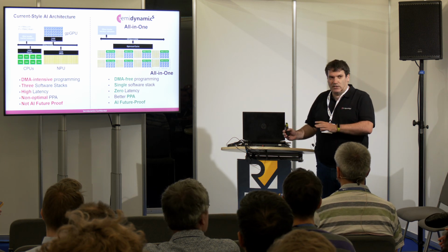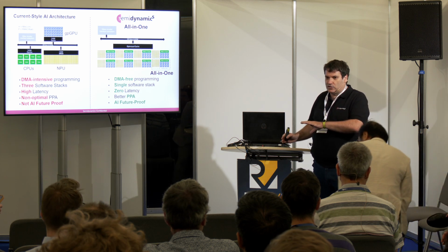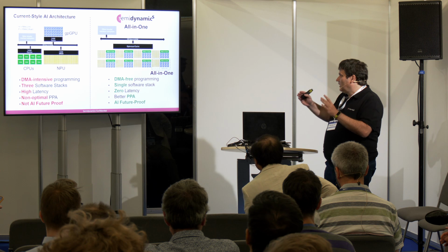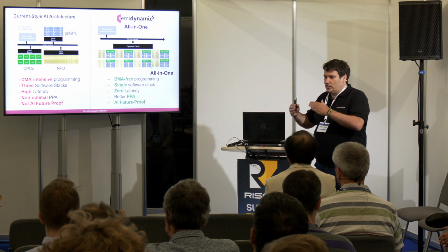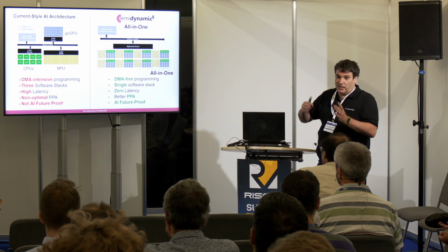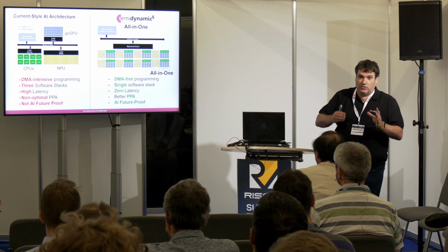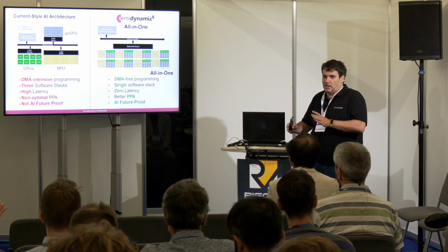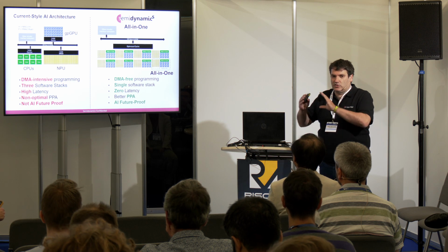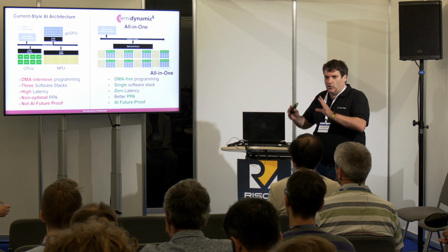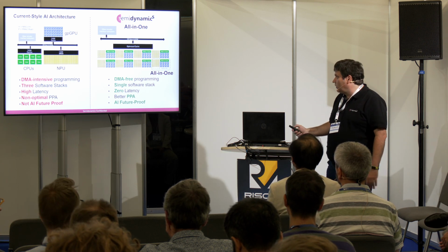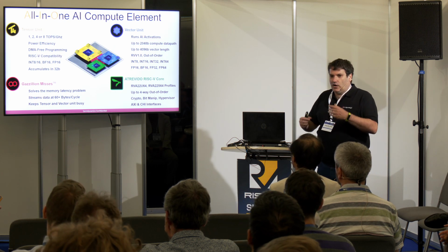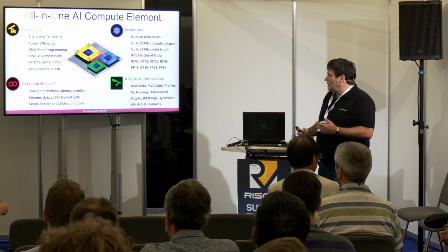We have zero latency because the data is shared in a single place. The vector unit and the tensor unit are going to share the register file, and they share the architectural state of the whole thing. The latency of moving data now becomes zero because they share the same space, and especially it will be a single software stack. For the programmers it will be great, because learning RISC-V will be enough to do all this programming. That's what we are trying to convey in this talk.